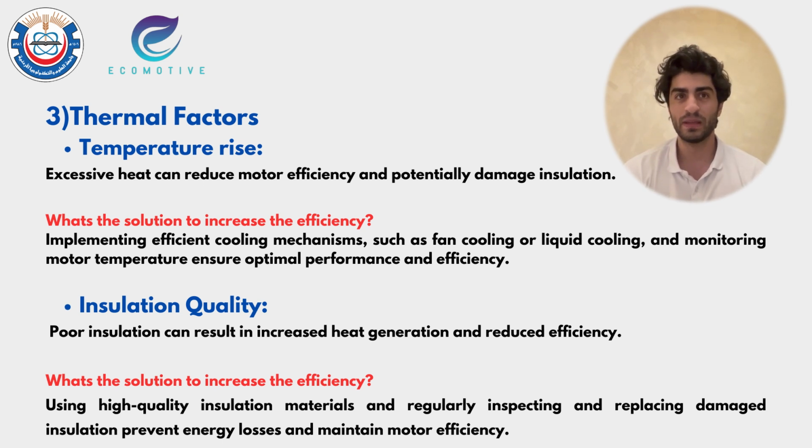Number three, thermal factors. Temperature rise. Excessive heat can reduce motor efficiency and potentially damage insulation. So what's the solution? Implementing efficient cooling mechanisms such as fan cooling or liquid cooling, and keeping an eye on motor temperature, ensures optimal performance and efficiency.